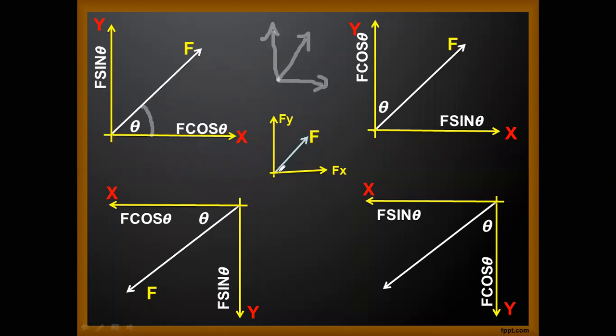Here you see this inclined force has been split into a horizontal component and a vertical component. What does the principle of resolution say? Even if you split this individual force into two components, the net effect of this individual force will be the same as the total effect caused by these two particular forces. So if the inclined force is there, then we can easily resolve the force into horizontal component and vertical component.